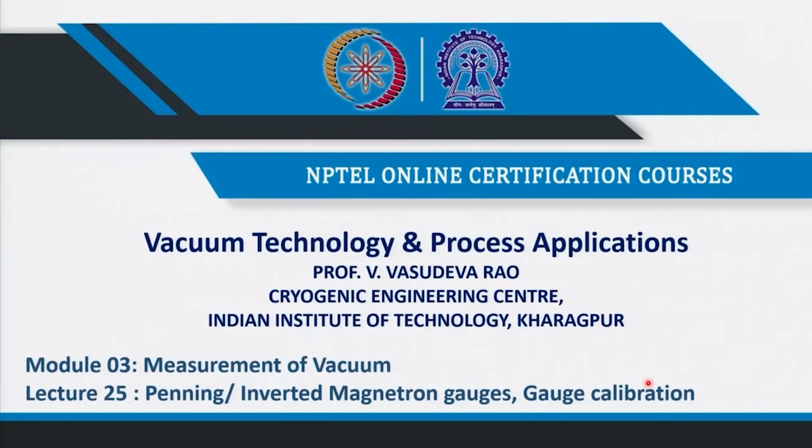We have seen Bourdon gauges, which are standard mechanical gauges of high pressure, extended towards this side. So, all these gauges we have seen for different purposes. They have got sensitivities and ruggedness and ranges applicable at various levels of vacuum. But now our game is towards high vacuum, ultra high vacuum. So, there we have seen the Bayard-Alpert gauge in the last class, how ionization is used.